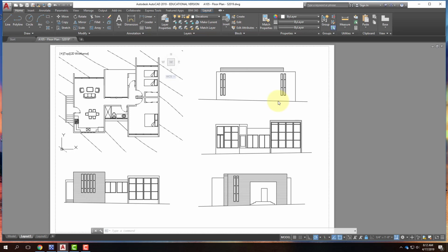The other thing that shows up in Paperspace is line types. Some of you had put line types on, used a hidden line, for example, and said, wait a minute, I can't see any of the dashes. That's okay. It shows up in Paperspace. That's where you're going to see the hidden dashes, etc. So everything's geared toward setting up in Paperspace.